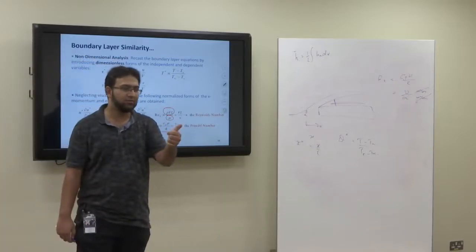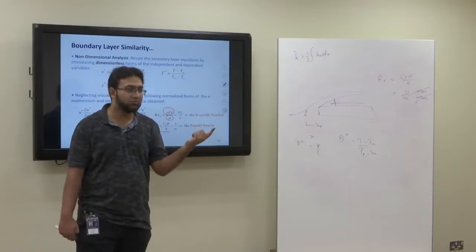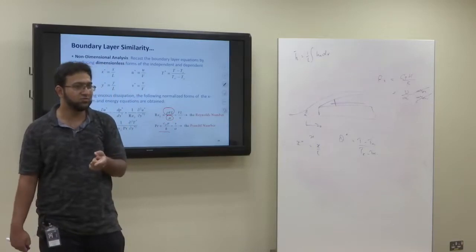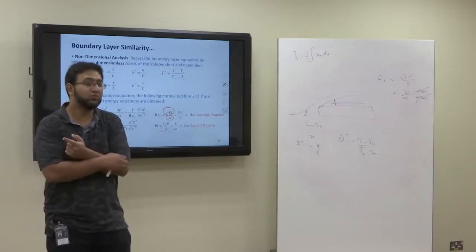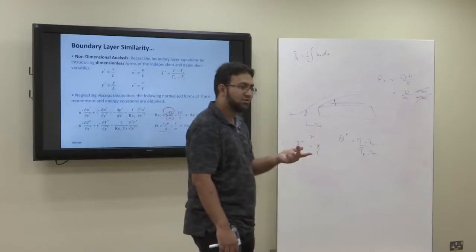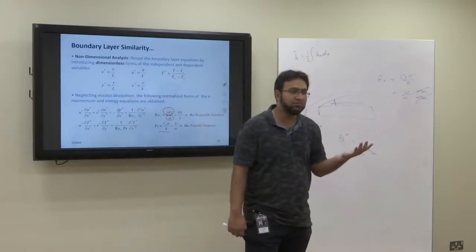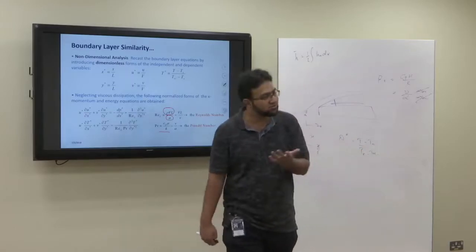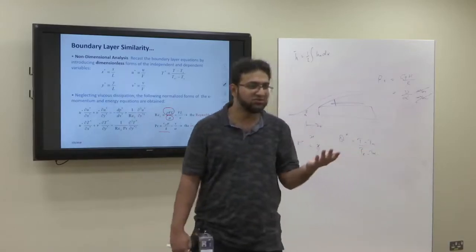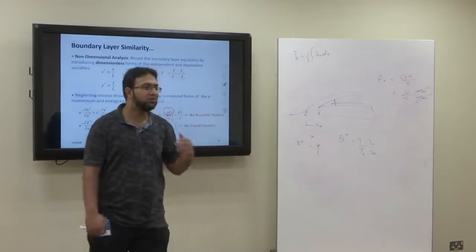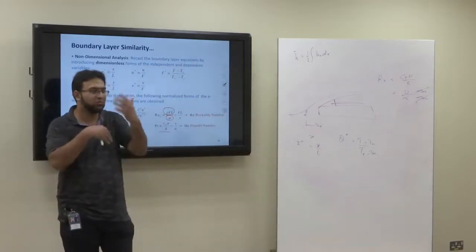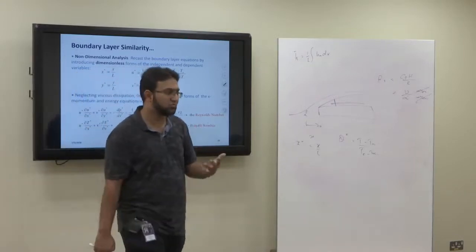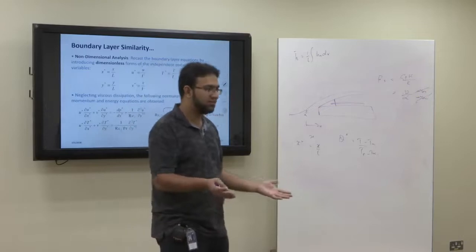I will repeat again. Reynolds number is a ratio of 2 forces, inertia force over viscous force. Prandtl number is a ratio of 2 diffusivities. Biot number is a ratio of 2 resistances. Fourier number is a ratio of 2 energies. So what each number in physical terms is a ratio of is something important from the short questions point of view, because that's a physical understanding.